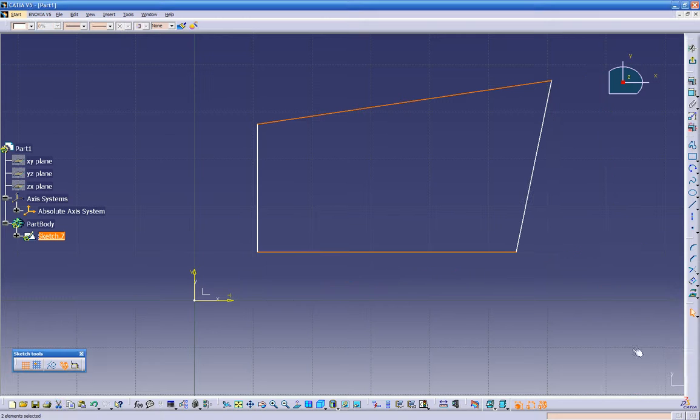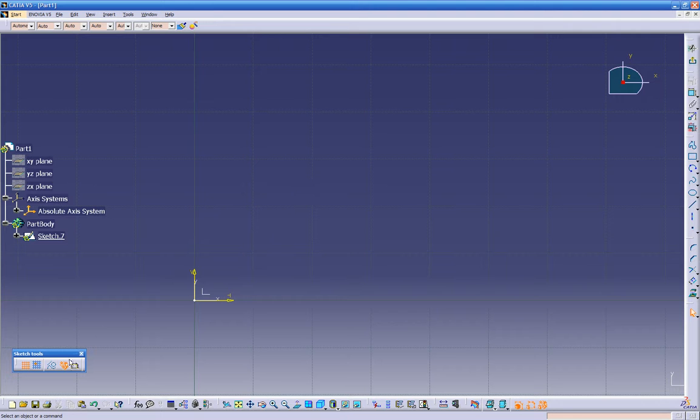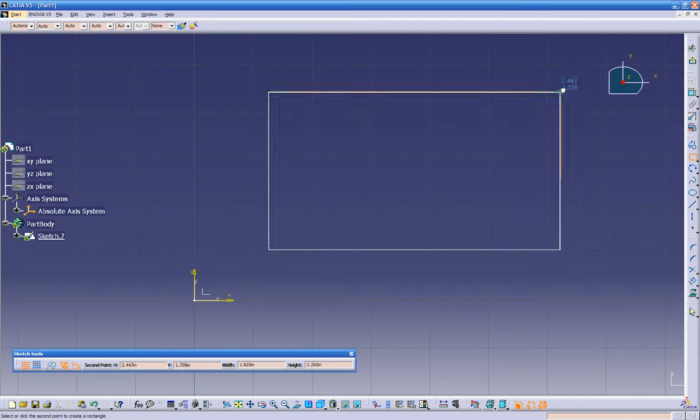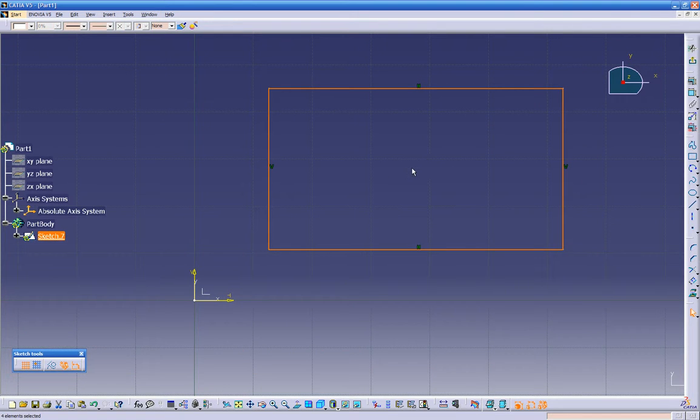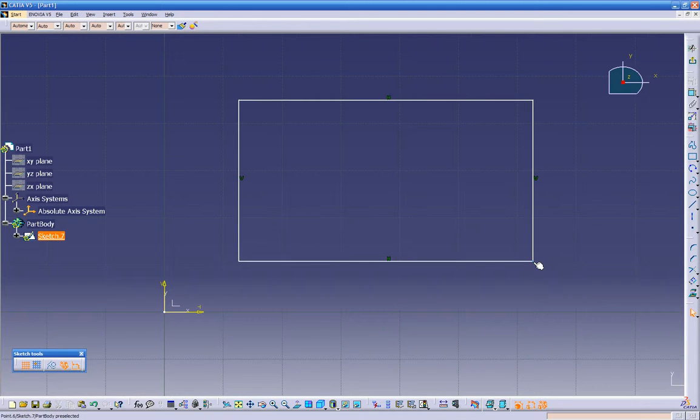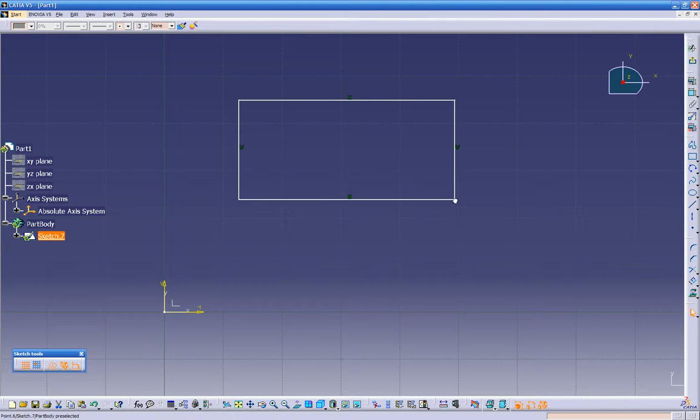So let's cancel this. Let's delete this rectangle, and let's try it again with this option already highlighted. And the same thing with the dimensional constraint. So usually, for my preferences, I like to have both of them activated. So in this case, once you create a rectangle, it automatically knows that this is a vertical line, horizontal, and horizontal. And if we try to move it like the previous rectangle, we cannot change it.